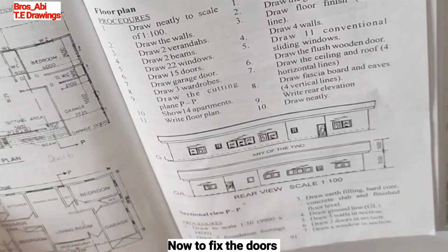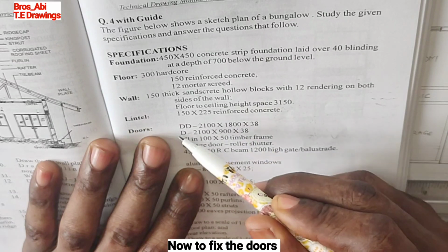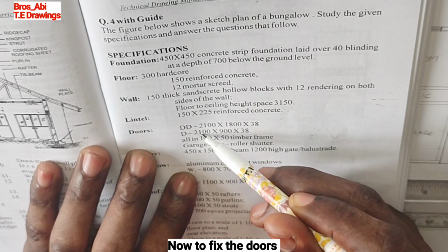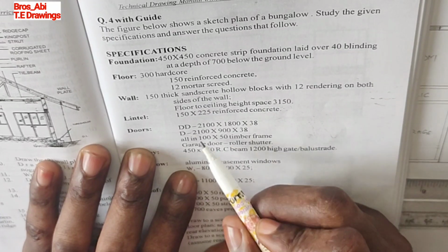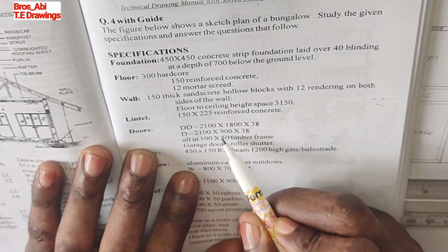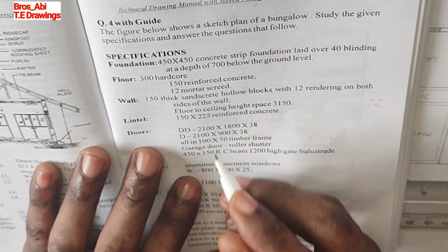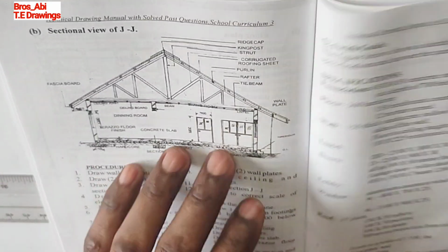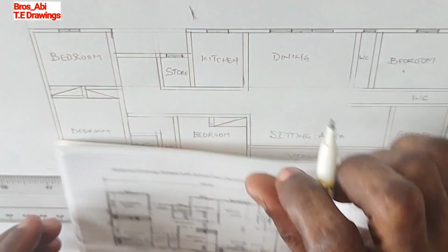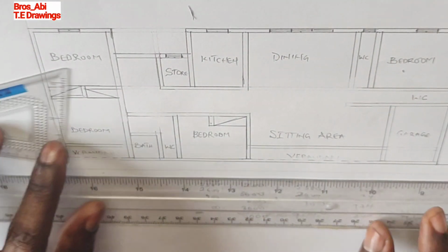Let's go back to the specification for the door. The door we have 2100 by 900 and 2100 by 1800. Now 2100 is for the height, while 900 is for the width, 1800 is also the width if it is double door. If it is single door, 900. So here we have single door, so we'll measure from here upward 900.